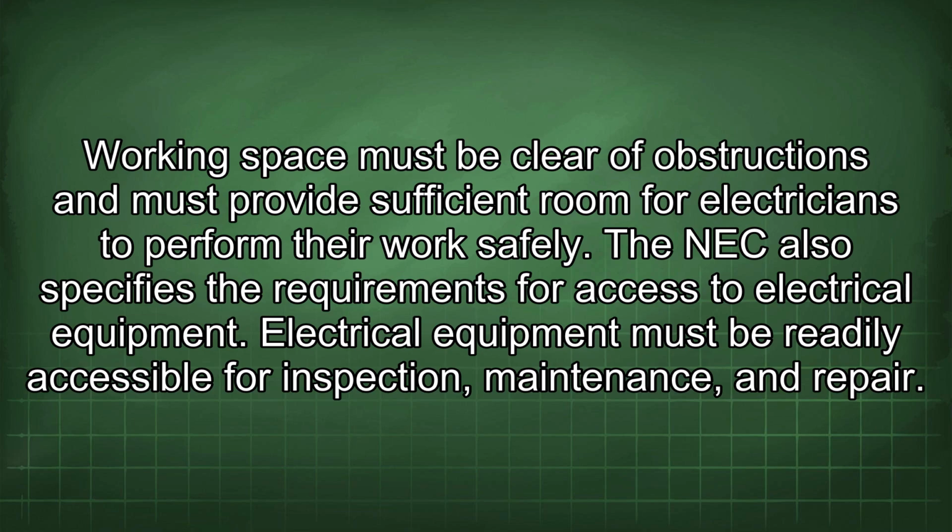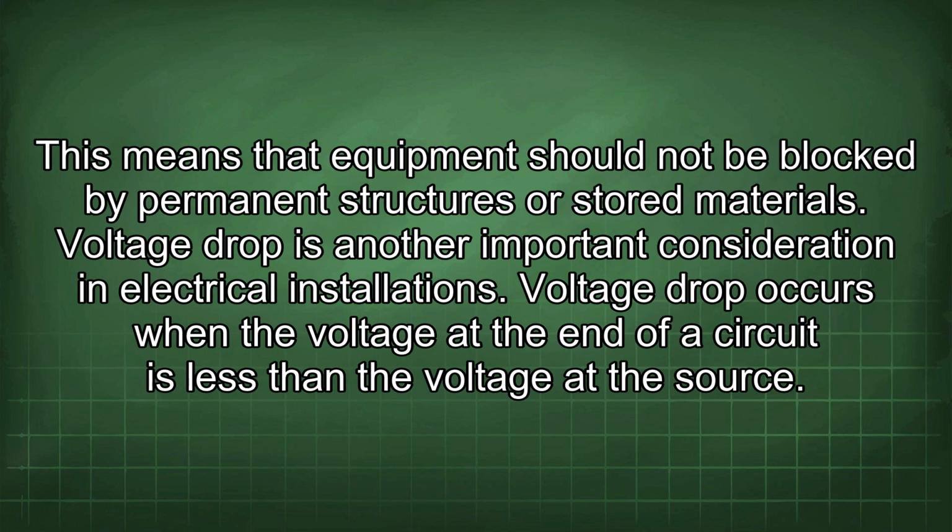The NEC also specifies the requirements for access to electrical equipment. Electrical equipment must be readily accessible for inspection, maintenance, and repair. This means that equipment should not be blocked by permanent structures or stored materials.